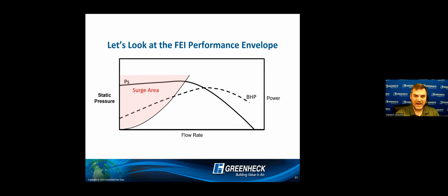So actually, let's go back to a fan curve and kind of overlay here. I've got my fan curve. I've got my brake horsepower shown, my do not operate zone in red. Let's throw a couple things on here. Number one, operating in a low efficiency point of that fan's operation or capability, right? So this is going to be low efficiency and higher sound. Then I've got that, what was a blue circle. Now I've got the operation of this fan in a higher efficiency and lower sound because it's in a more efficient spot of its own operation.